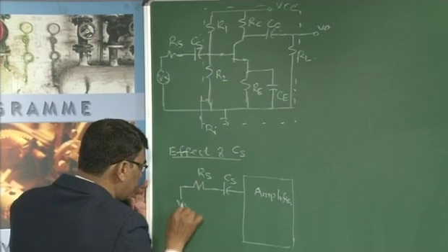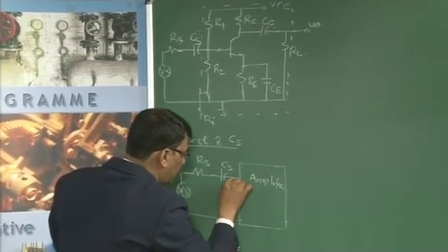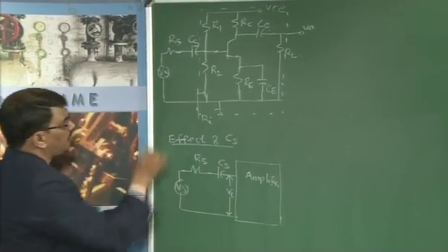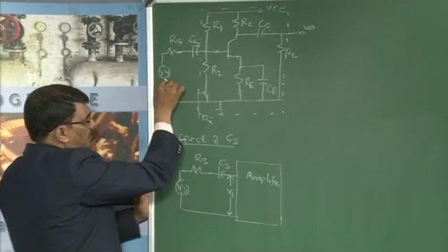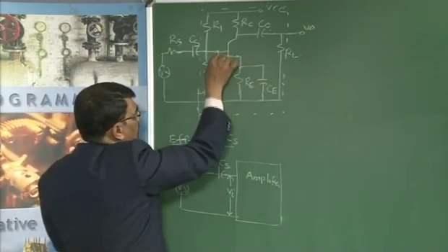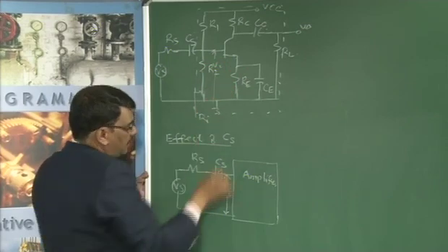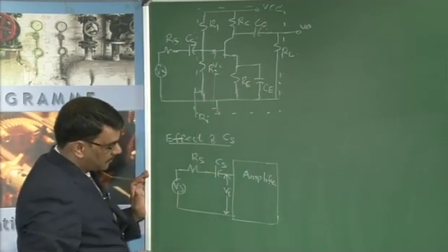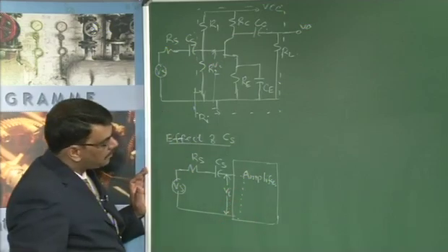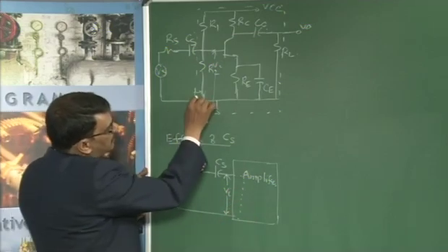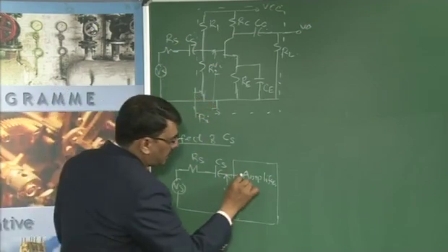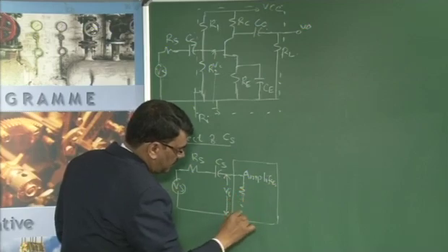The input is connected between these points. The voltage across this is denoted Vi. Even if you apply an input voltage via the source voltage Vs, the voltage that appears across the base emitter terminal is Vi. When you look into the amplifier, the input resistance Ri is present.